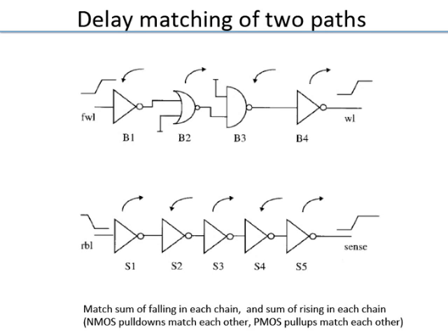So the two things we are saying here is, try to use a replica of whatever you are doing. This concept of replica is used in many different situations. For example, in analog circuits, when you want to bias something, you have a main circuit, and you take a copy of itself and set up the connection so that it generates the bias voltage. The replica and whatever you want to do track well, because it's the same circuit topology, probably even the same layout, everything is the same, so they match well.